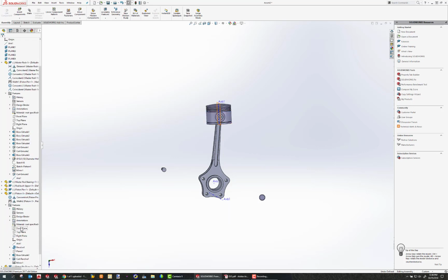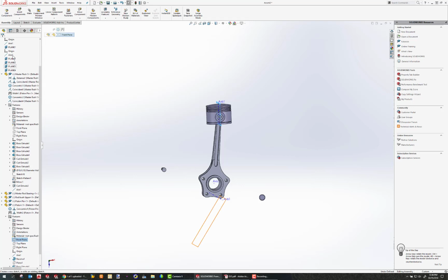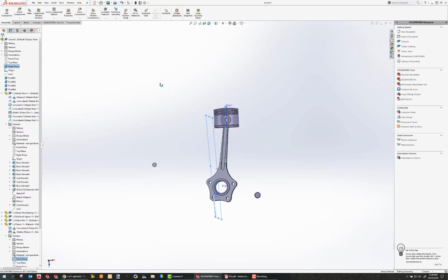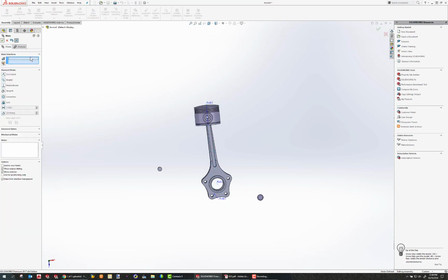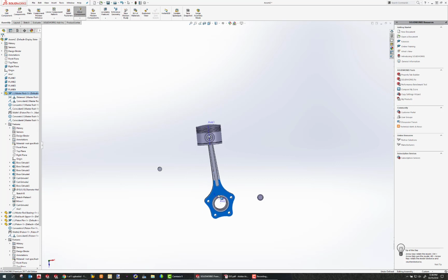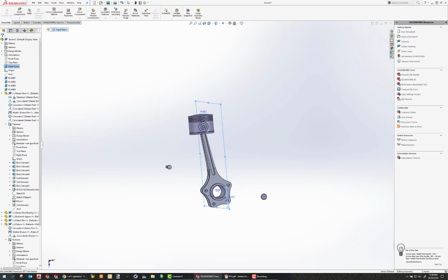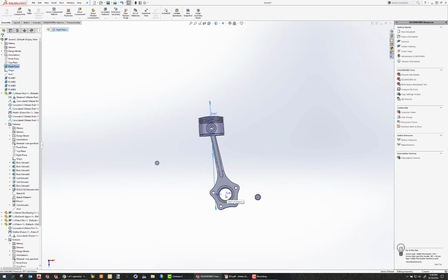So if I look at the piston front plane and the right plane of my assembly and mate those coincident, hopefully you can see what happens here is now when I move, I get the engine motion that I'm looking for, because this piston is constrained because its top plane or front plane, whatever it was, is coincident with the right plane of my assembly. And so it's always going to be there, but my axis is always going to be 40 millimeters offset. So the axis is always going to rotate around the axis of my assembly there.